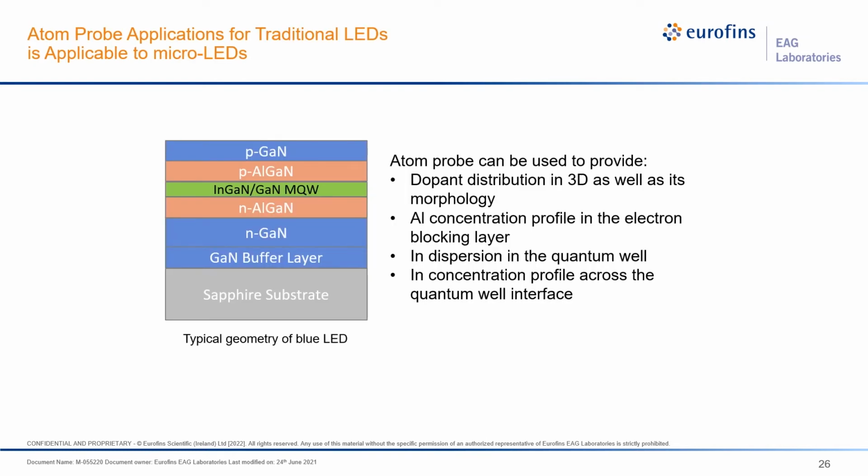So now how can we apply this to micro LEDs? We can use atom probe to look at an epitaxial structure like this in a micro LED. We have positionability, like we can effectively select where we want to go to make the sample, and that's really just limited by the resolution in the SEM and FIB itself. So that's nanometer location precision to go after things.